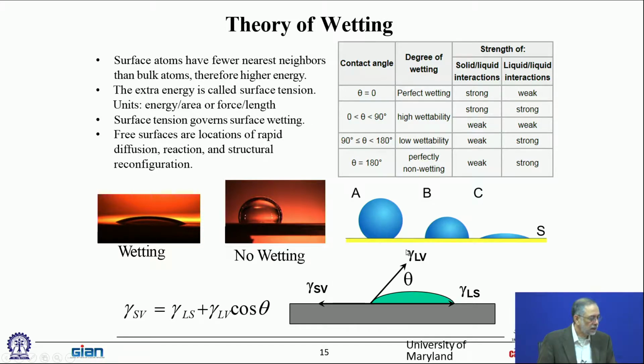Okay, all right, and of course it's actually a tri-material interface. You have some air or gaseous medium here and two metals, so that's a tri-material interface. So that's why you're seeing solid to vapor, liquid to solid, so that's a liquid, solid, and vapor. So you have a tri-material interface, so you're looking at different surface energy terms for each of those combinations. Okay. And the point is that you're looking for a plating material and a solder material that wets each other well. Not all materials will wet each other equally well. It depends on the surface energy characteristics.